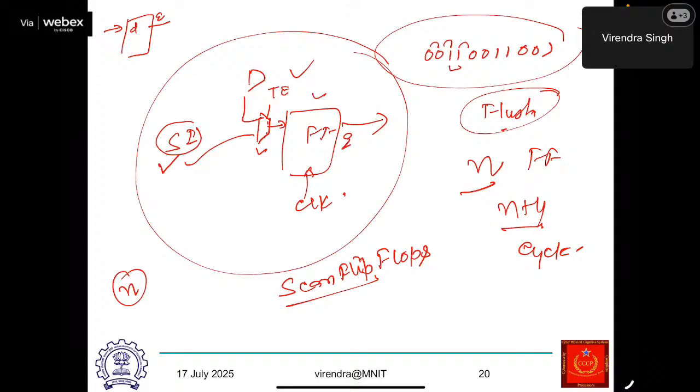That will have an impact on the cost, because the cost will become double, because now the test time is more or less dominated by the time during which you load the flip flops and unload the flip flops. And if this time becomes double, in that case my total test cost will become double. You don't want to have that.